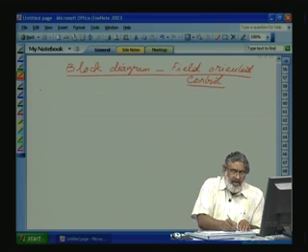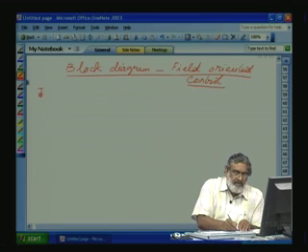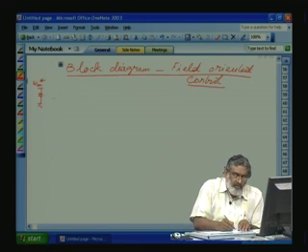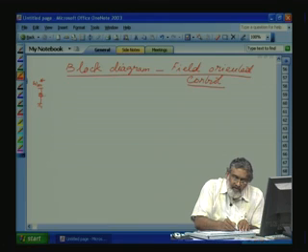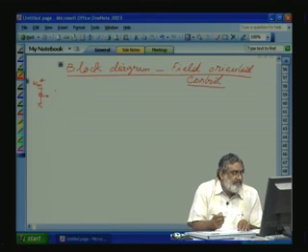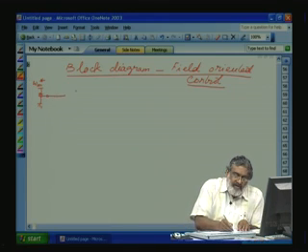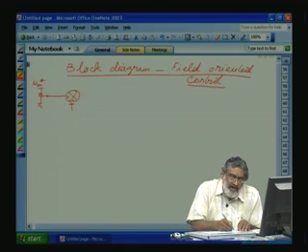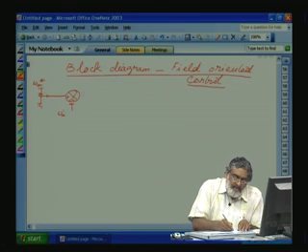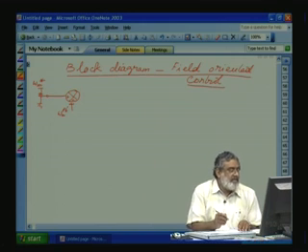See, we are giving the omega m speed reference. This we will give it. So there should be a feedback, omega m feedback. That we can take it from the tacho.